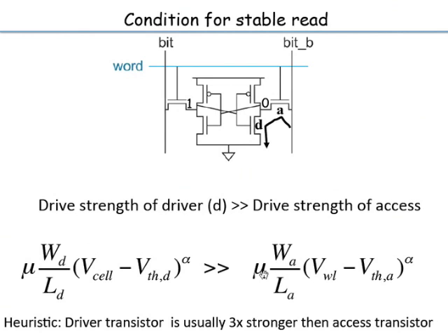Let us say everything is the same to begin with. Now you want to improve this. So you can increase the width of the transistors. Okay, that is one. You can reduce the threshold. Now what is the problem with reducing the threshold? Leakage. And that is a very, very big problem, because you will have multi-million cells like this. So you cannot afford to have too much leakage in these cells. The leakage has to be kept as small as possible. So you kind of want to have larger threshold voltages.